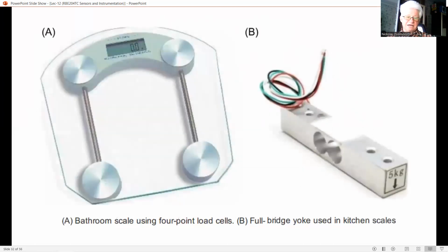Another way to realize small sensitive accelerometers is the use of thin films of PZT, typically from 1 to 5 micrometers. In this case, the piezoelectric material is one of a sandwich of thin layers deposited on a silicon substrate. Other layers serve as electrodes and isolation. The seismic mass is formed by selective etching of the substrate, resulting in a mass spring system similar to the one shown in this figure. The structure is sensitive in 3 directions,